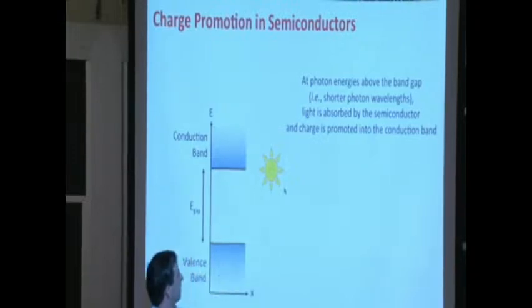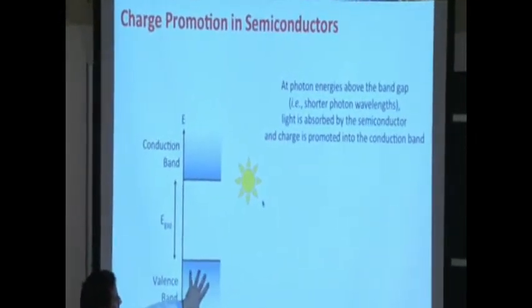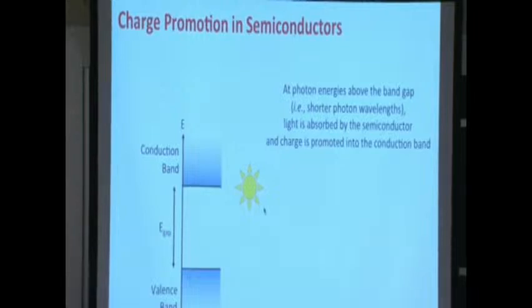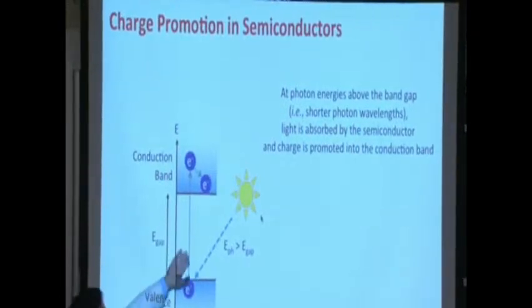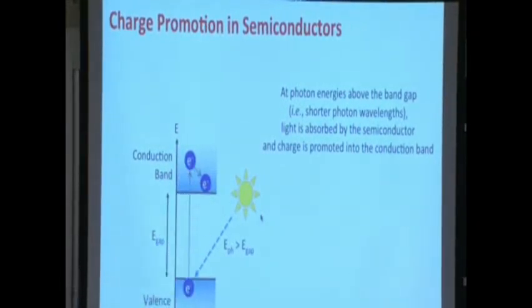Now we have sunlight here outside of our device, and it's going to be shining light onto the semiconductor crystal. So what happens? Well, we know intuitively that charge should be excited from a bound state to an unbound state where it can move around the material, but not all light serves this function. If we have a photon that has an energy above the band gap energy, so E photon, meaning the energy of the incident photon, is greater than E gap, the energy band gap, then we'll have an excitation of charge. We'll have an electron taken from somewhere here, brought up to a higher excited state, and it might come to settle down at the bottom of that band of states that is allowed, just a settling, if you will.